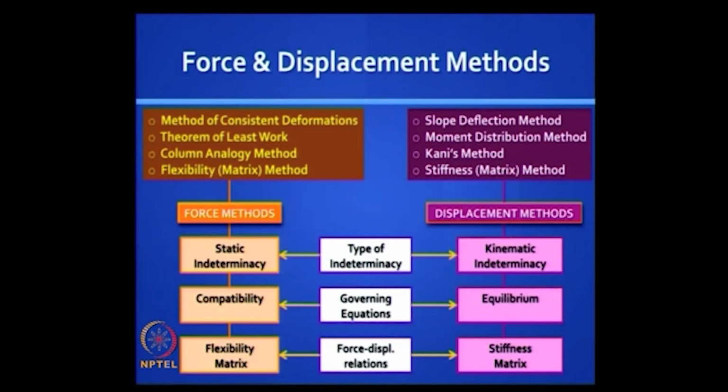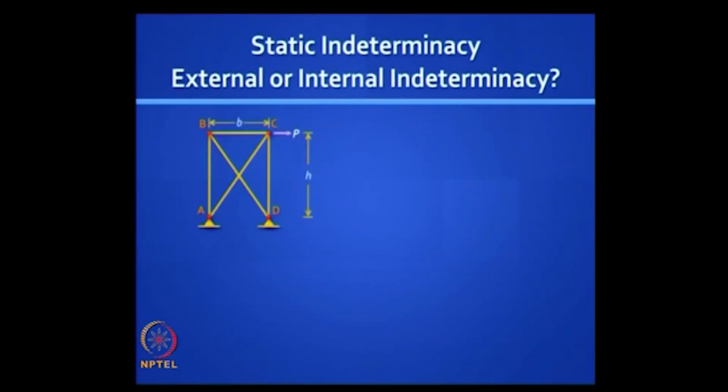As I mentioned, the first 3 lectures will focus on force methods, and the next 4 lectures will focus on displacement methods. Let us begin with something you know very well. Look at this pin jointed frame or truss, plain truss. What is the degree of indeterminacy? Static indeterminacy. Yes? 2, very good. Would you describe this, is it 2?